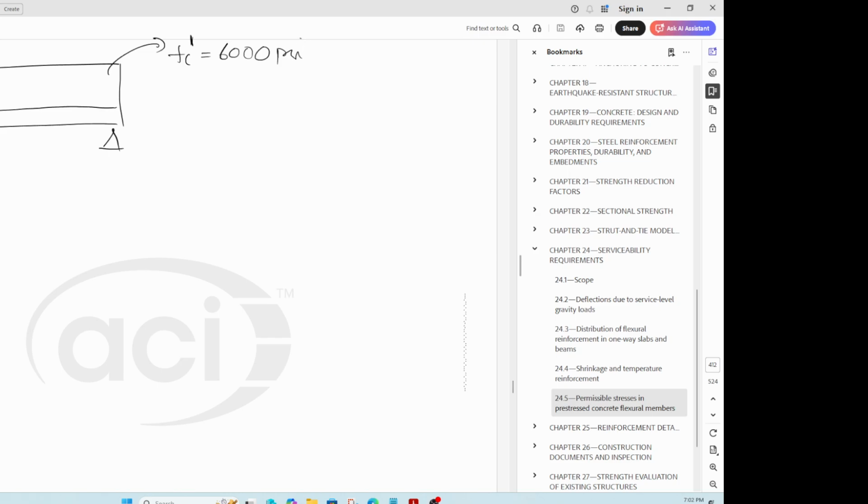And you have already installed some dead load. Maybe there is another slab sitting on this particular beam, so you have your UDL because of the dead load, which is superimposed, plus you also have UDL, that is another dead load, but this is self weight, right? So now you see new loads being introduced, correct? At this stage, this is a final stage, but this is a serviceability stage wherein you are still not allowing your live load, right? You are not allowing your cars and other things on the beam. So you only have dead load and you have self weight, correct?